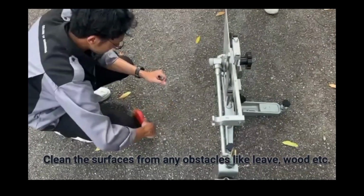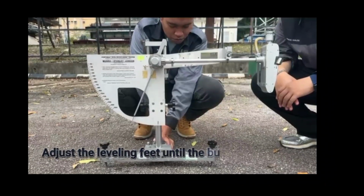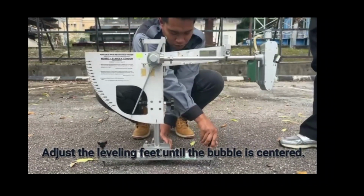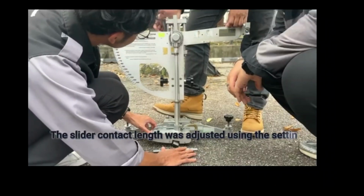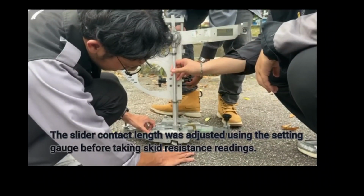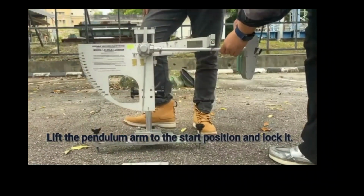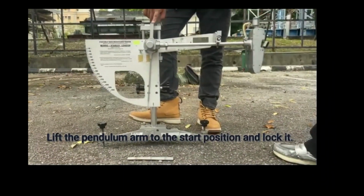Clean the surface from any obstacle like leaves, wood, etc. Adjust the leveling feet until the bubble is centered. The slider contact length was adjusted using the setting gauge before taking skid resistant readings. Lift the pendulum arm to the start position and lock it.